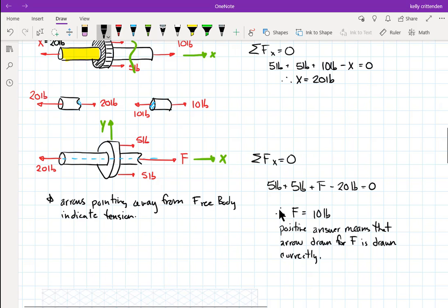In general, metals don't behave any different in tension or compression. They're pretty much the same, but other materials like concrete behave very differently in tension and compression. So it is important generally in metals, which is most of what this course will have is metals and a little bit of wood material every now and then mixed in. Generally, metals are the same in tension and compression as far as strength goes. But you still need to know.